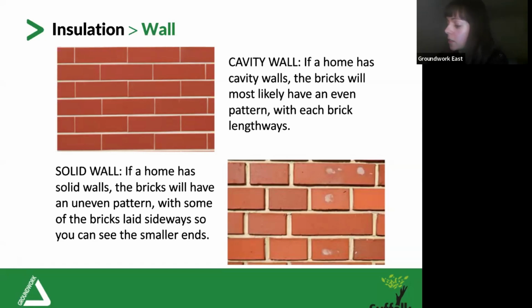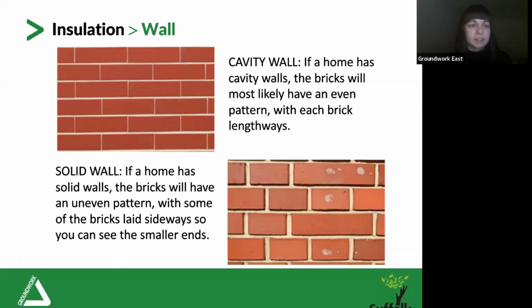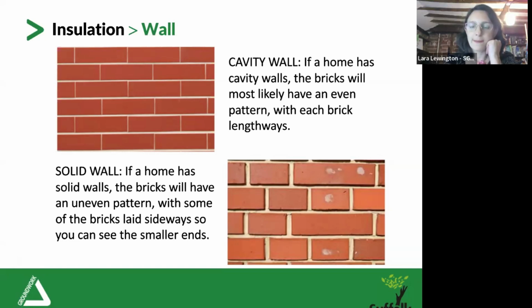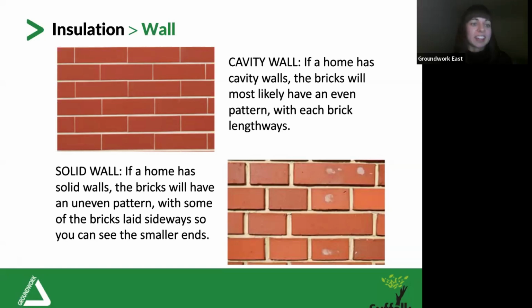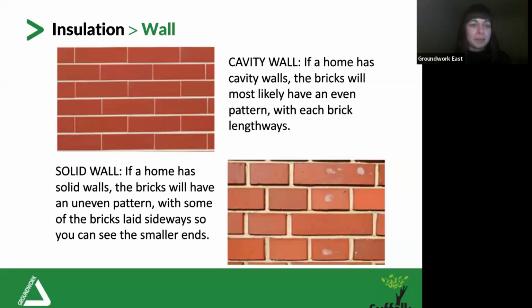Also, regarding internal wall insulation, obviously one has to take light switches and other things off the wall and extend the cables to the new light switch level. There's quite a lot of other things that's relevant to. Windows, you have a bigger recess. Yes, for windows and doors. That's a really good point, thank you. Chimney breasts, and radiators, plumbing, whatever is on that wall will need to be adapted.